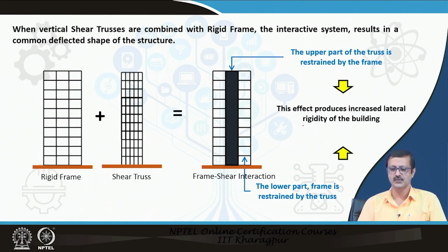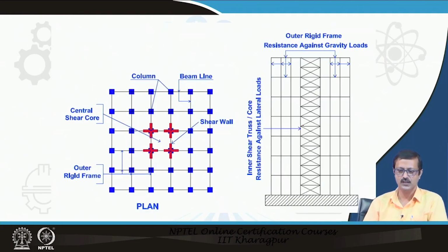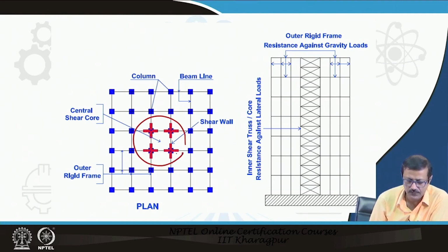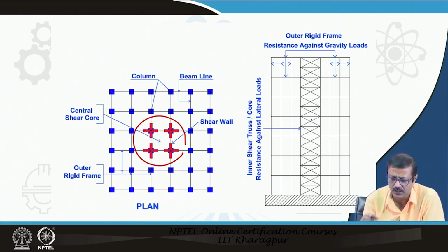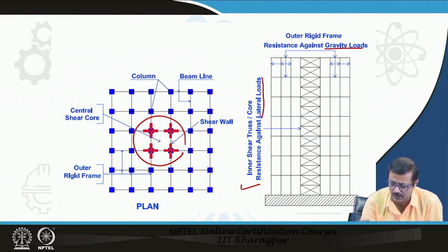Finally, in effect, we can have lateral rigidity of the building along with vertical or gravity load transmission. This is again a skeleton figure. You have a core inbuilt inside the frame system. They take a larger influence floor plate area, an internal core, and some kind of resisting frame. The outside is the gravity load resisting, and the central area takes up the lateral resisting load. So this is lateral, and this is again the gravity.